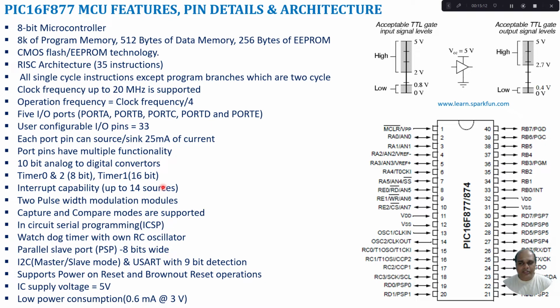Upon request, the CPU can respond to that interrupt by providing the necessary program execution related to that input or output device. So an interrupt comes from a peripheral device. On receiving that interrupt, the CPU can run a program which is nothing but the interrupt service routine. It can run a program related to that interrupt, thereby servicing that interrupt.